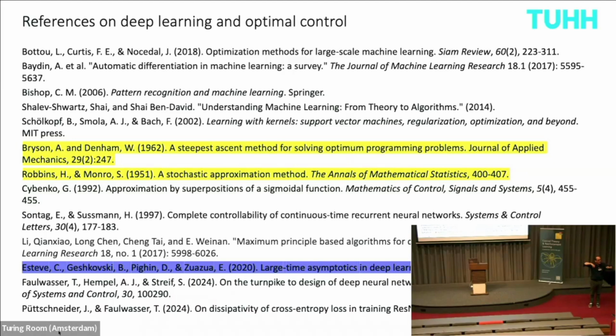Because there are ways of how to handle unstable dynamics in numerical optimal control. That's called multiple shooting, where you integrate over shorter horizons and force the solutions to converge over the iterations. But I'm not aware that anyone would have dared to challenge the big toolboxes by deploying such methods. But there are ways there. It's not by the discretization that you lose that, or that you would get a way around this. I would suggest, if this really puzzles you, take a look at what the tricks are that are applied in numerical optimal control to precisely avoid this from happening.